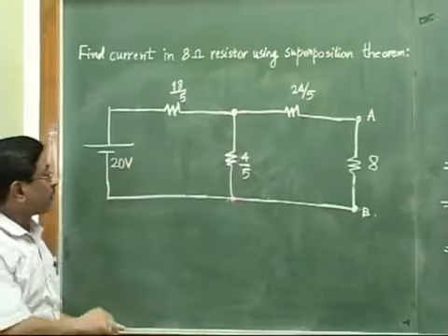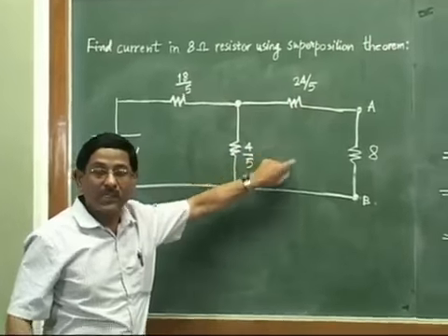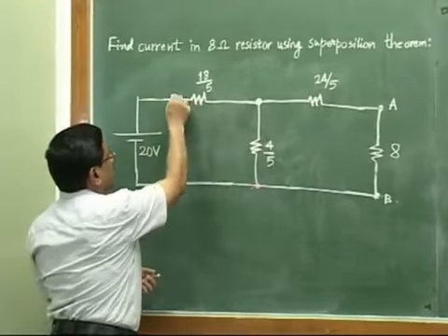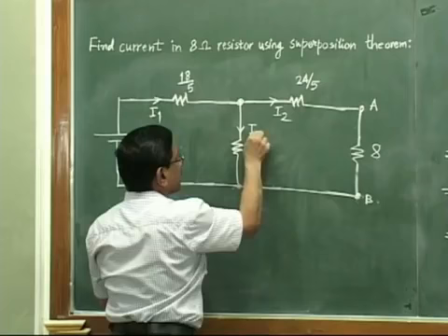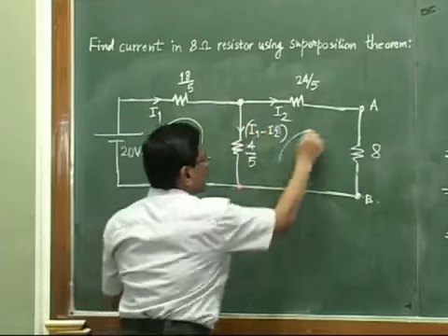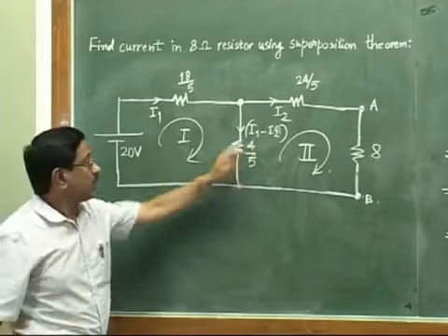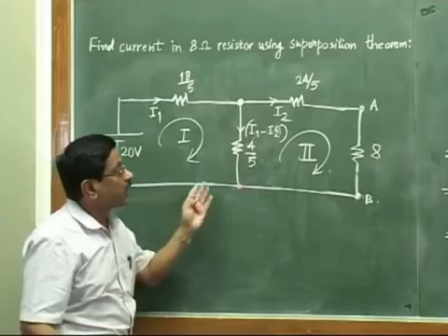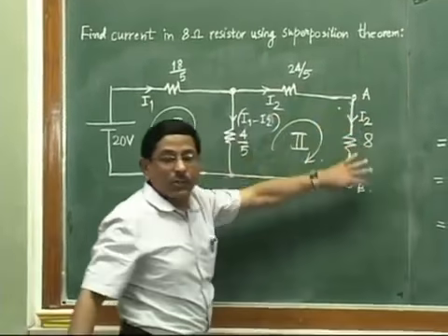Okay? And now see, if we distribute the currents, you will find that there are only two meshes, so you will get only two current variables. So you have to distribute current like this: I1 here, say I2 here, then I1 minus I2 here, and then you select these two loops, loop 1 and loop 2. Because your variables are only 2, you write the equations, solve them, and finally in which value are we interested? In this I2, because in this case this I2 flows here. Okay? So this is one way.